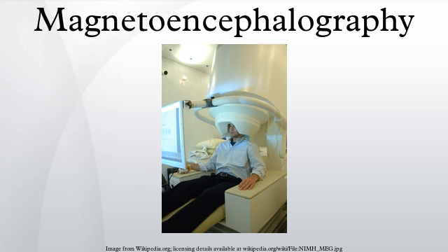Magnetic shielding. Since the magnetic signals emitted by the brain are on the order of a few femtoteslas, shielding from external magnetic signals, including the Earth's magnetic field, is necessary. Appropriate magnetic shielding can be obtained by constructing rooms made of aluminium and mu metal for reducing high-frequency and low-frequency noise, respectively.